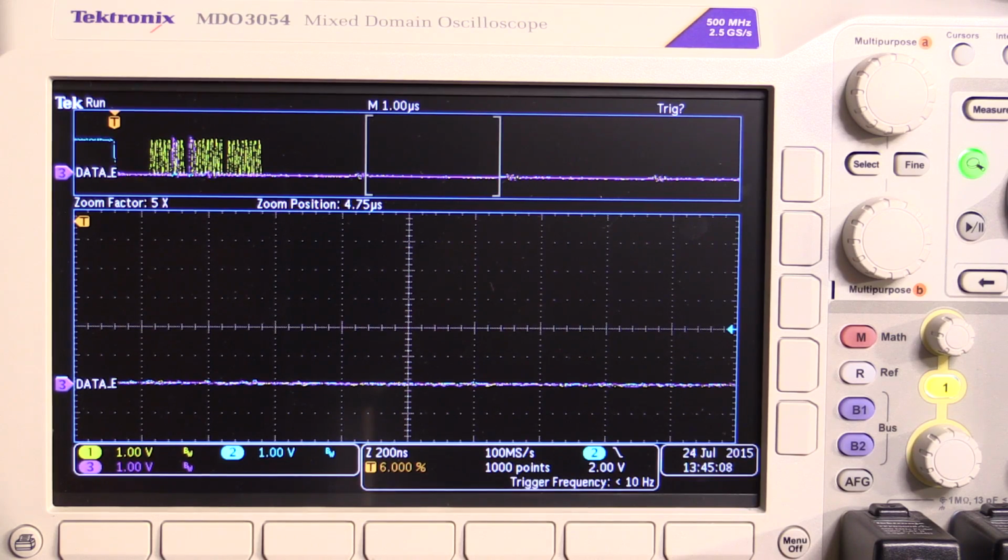If you wanted to produce some high frequency signals, you could offload the work of driving the signals to a microcontroller, which is better apt at doing that tight, consistent timing, and just have the control mechanics in the Raspberry Pi. But in this case, I would at least expect to be able to get a few kilohertz of a sine wave out from a Raspberry Pi using the SPI bus to a DAC or something.